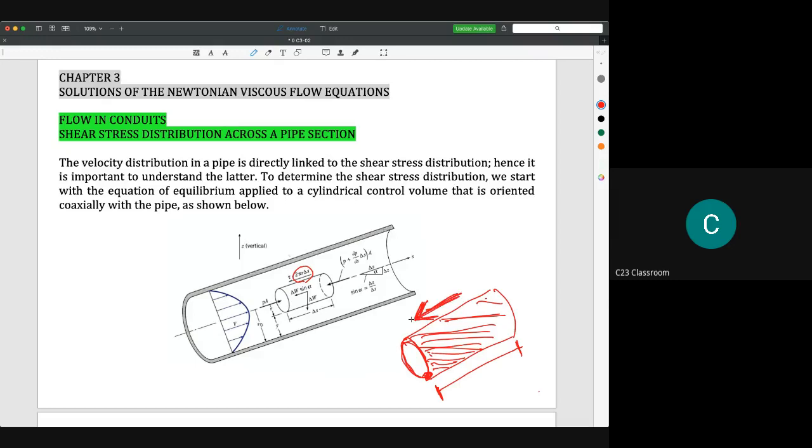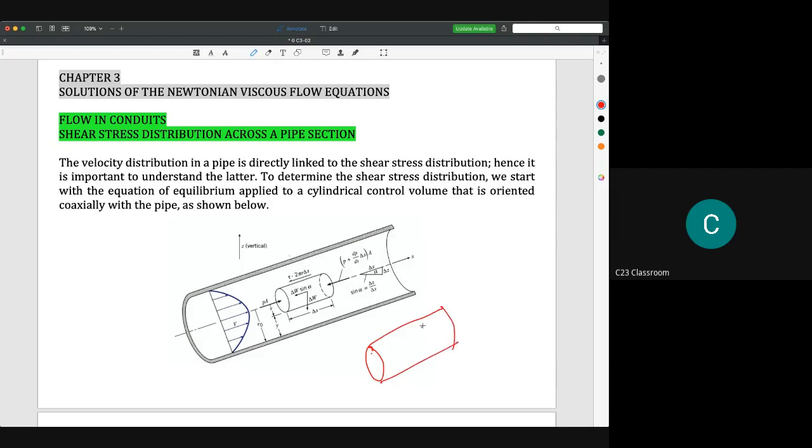So in the Couette flow, we have a plate here and also a plate here. That's why we have shear stress in both directions like this one, because the nearer the fluid molecule to the solid surface, the shear stress will increase. Okay, that's the difference. And this arrow actually represents all the directions at the circular element here. It means that the shear stress here will act like that and so on.